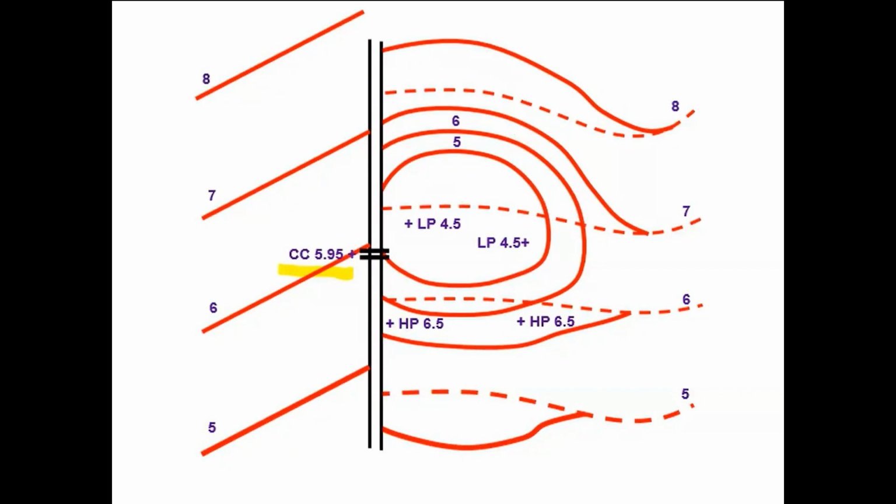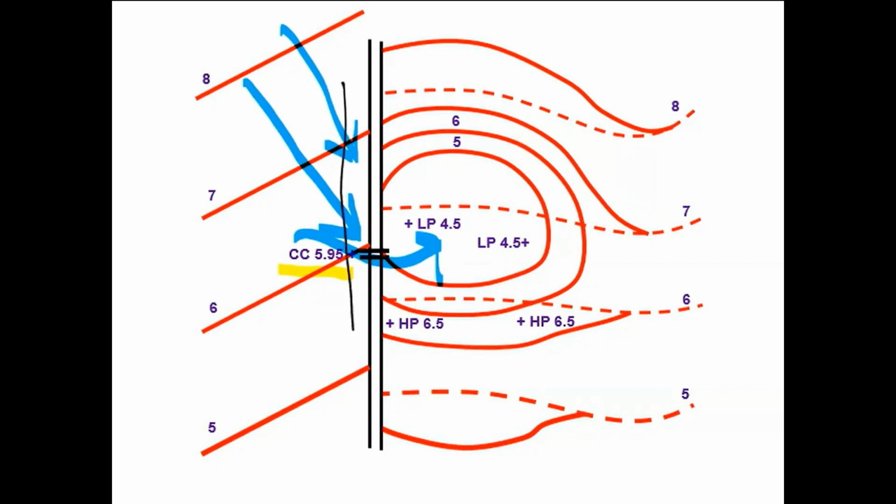We need to talk about where you choose to place your curb cuts. And the placement of curb cuts is actually simpler than it seems at first. We have water running down through the parking lot, and we have our curb cut located so that the water would then run into our bioretention system. The thing that we have to discuss in terms of curb cut location is how far up or down this curb is the appropriate location for a curb cut.